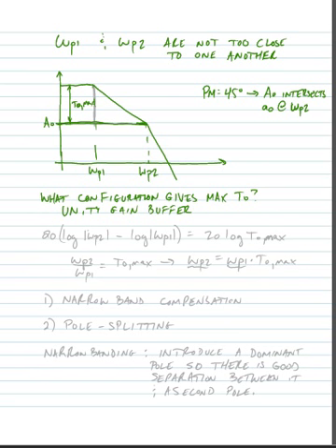All right, so if we take this section of the frequency response where we have the maximum loop gain at the first pole frequency and the difference between the two pole frequencies, we could write that 20 log of omega P2 minus 20 log of omega P1 is equal to 20 times the log of our maximum loop gain.